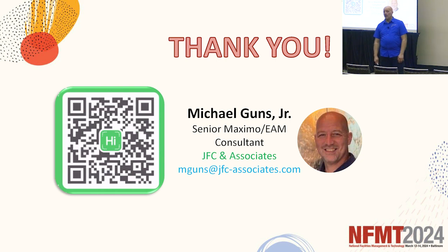Yes. The great thing about failure codes and reporting is it can be applied across the board. And it's relatively inexpensive, if not no expense, because you can apply these or create these failure codes yourself. If you need help with it, obviously, with consulting firms and that kind of thing, there's going to be a price there. But if you look at what caused that failure, you can do the 5 whys. Why did that happen? All right, why did that happen? You can do that basically with yourself or a couple of people.